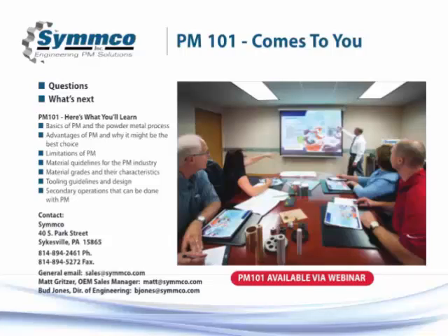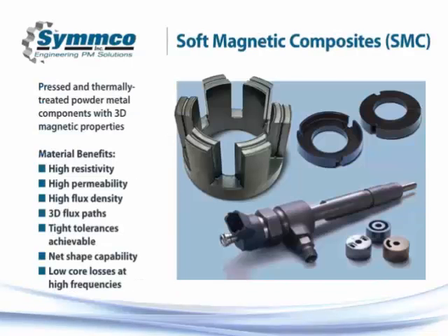Thanks. And what type of tolerances do you typically require on axial dimensions and diameter or bore dimensions? Wow, that's a great question. Two answers. The first will be somewhat of an avoidance, to be honest. The second is a little bit of general tolerancing. It's hard to say what our tolerances are. Axially, we're controlled by the press compaction, so there's more variation axially. If you look perpendicular to the direction of compression, typically the outside diameters and inside diameters are controlled by tooling. A little easier to control.